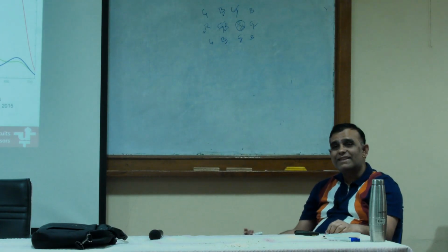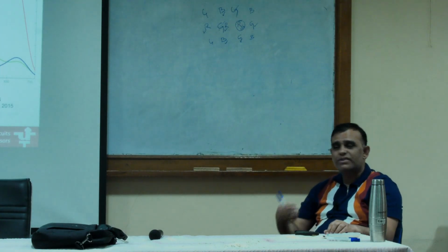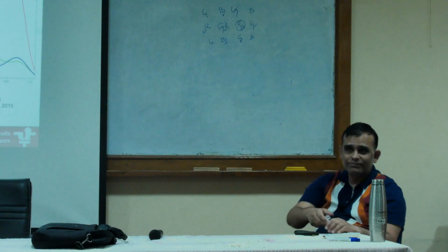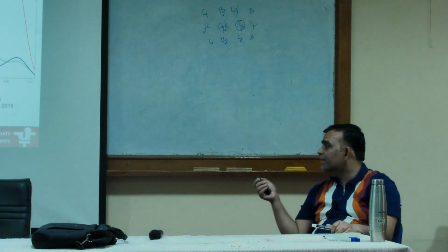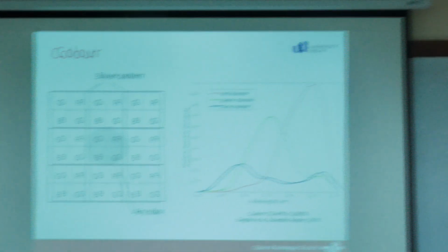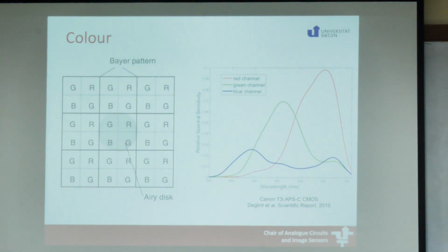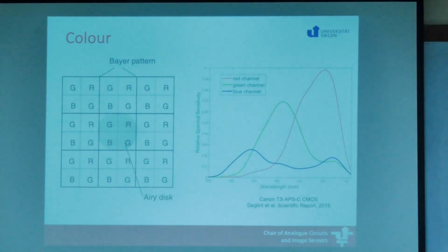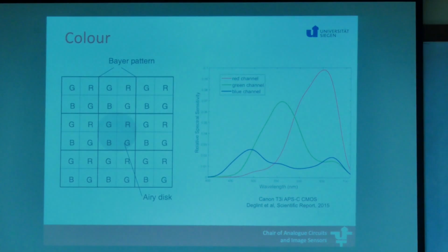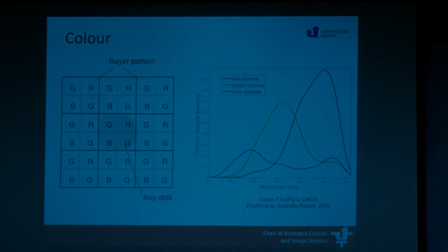So to some extent, it's an exercise in how you do debugging, and of course how good the color filters are. This debugging technique would have worked brilliantly if my color filter was blue, went up, and then green started here, went up, and came down. Now, most of these filters are some sort of polymer filter which are deposited post-chip fabrication. So once the chip has been made, we then put a pattern of micro lenses and a pattern of color filters. Okay.